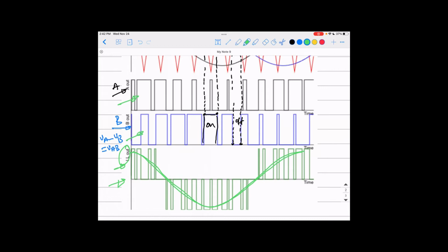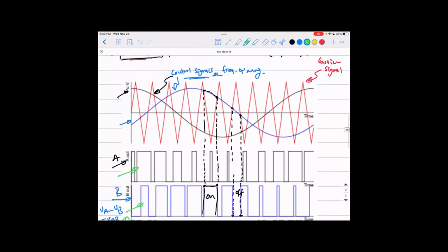So you have these pulses, and now you have the AC voltage outside. It's not purely sinusoidal like you see, it's some sort of pulses like that, and that's typical, so you don't get a very pure sinusoidal wave. You have harmonics inside them, and that's why we use filters to filter out as much of these harmonics as we can, to get as close to sinusoidal voltages. Again, refer back to your circuits courses where you dealt with filters. So you use filters after this circuit most of the time to get as close to the sinusoidal voltage as you can.